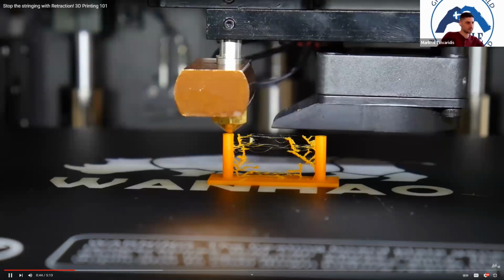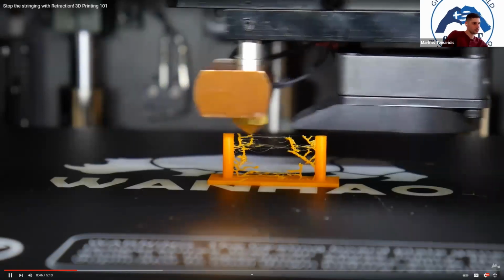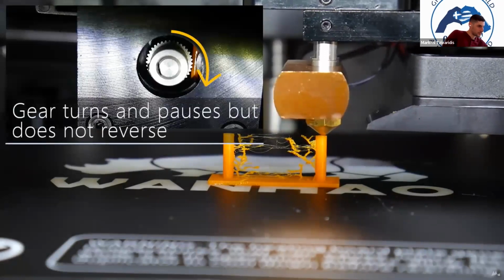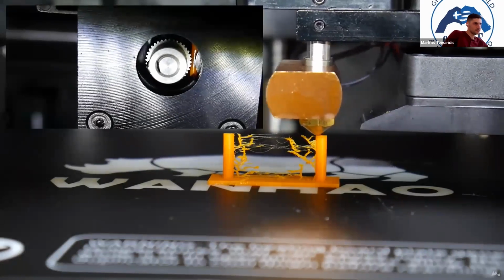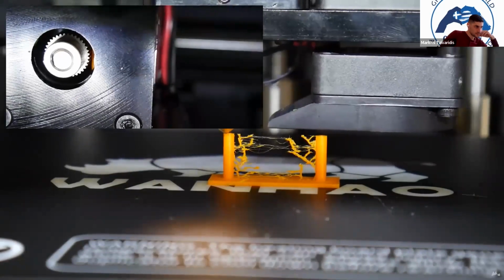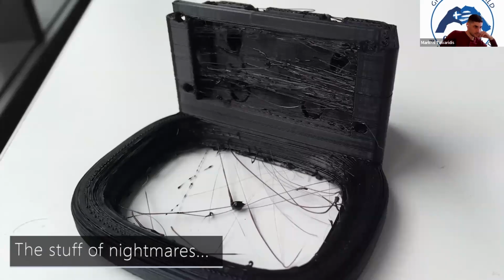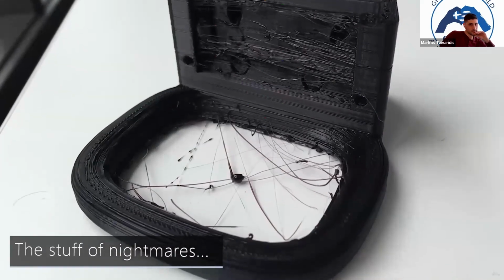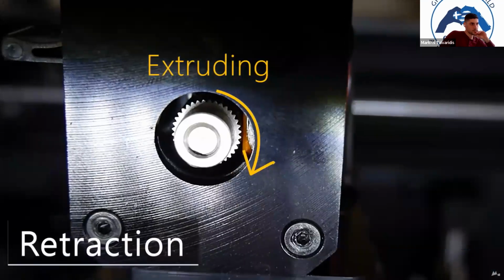Out as it moves between points of the print. You see, as the extruder pushes filament into the hot end, this creates pressure, and this pressure wants to equalize. So simply stopping the extruder won't actually stop plastic oozing out of the nozzle. So this can make a print look terrible, and while tweaking temperatures can help to some degrees, printing with no retraction will always leave a subpar result when printing complicated models. Okay, great Angus, but how do we stop stringing? Well, this is called retraction.